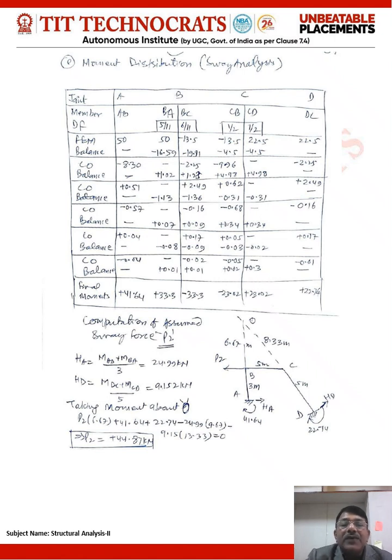Then after finding the values in the column AB, beam BC and column CD, with the calculated value of moment distribution factor, we can go for the moment distribution for the sway. At the end of the entire distribution, after running the cycle of correction 3 to 4 times, at the end you end up with some values at the base of the column or at the joint.